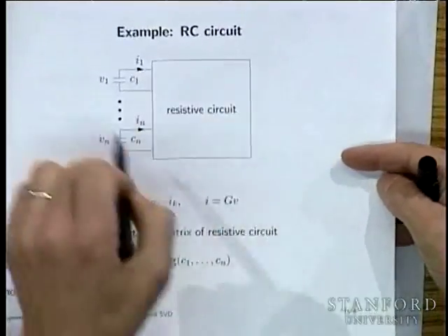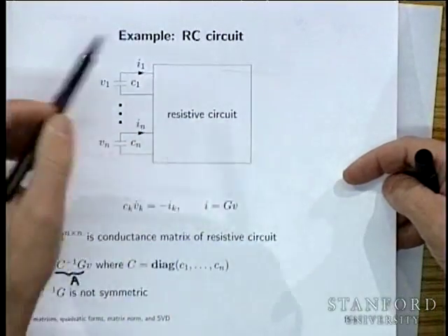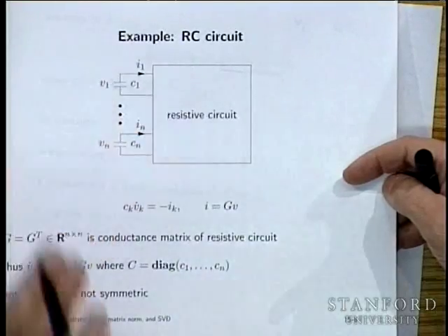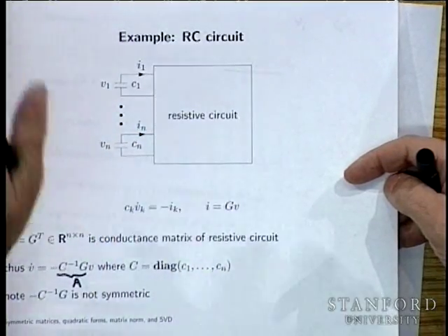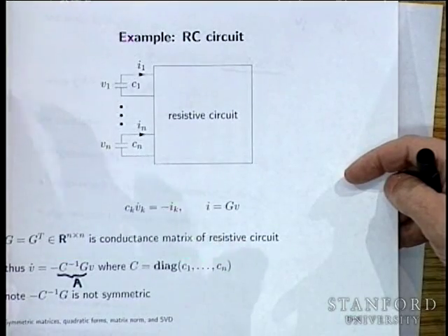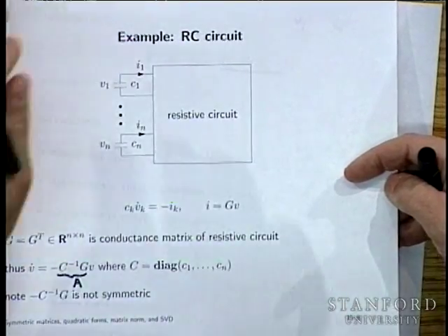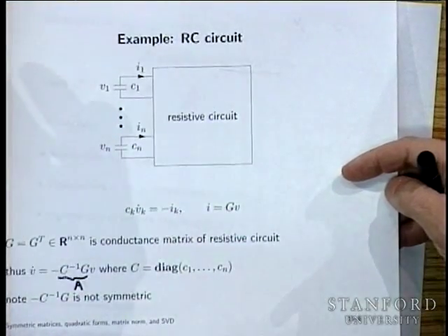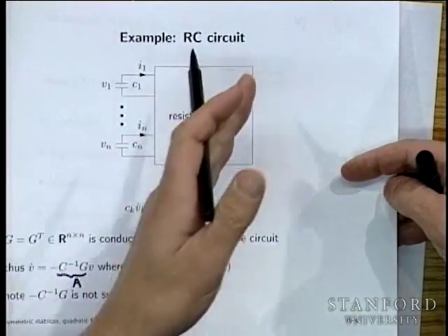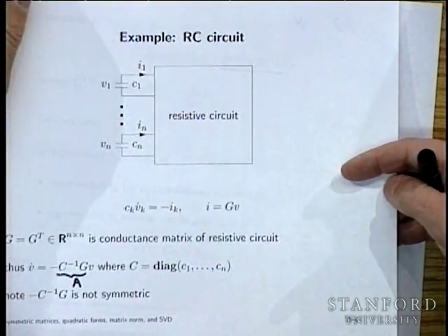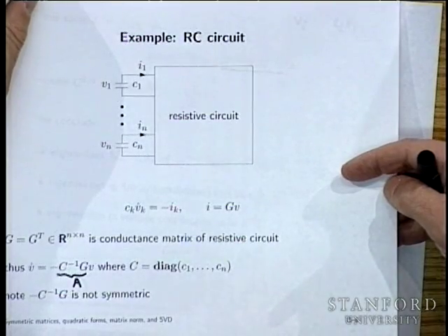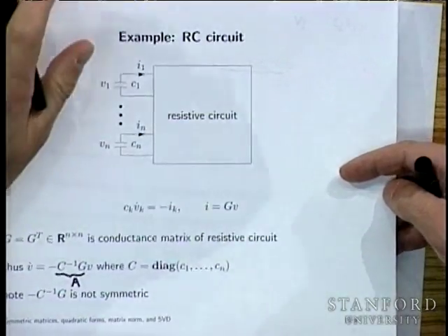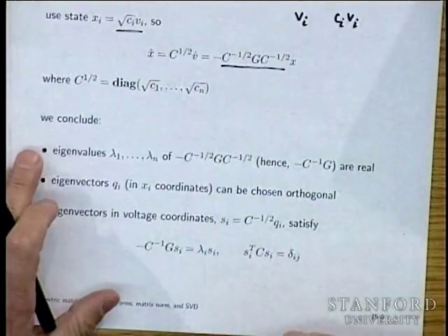So we recover something you probably know from undergraduate days or intuition or something like that. An RC circuit has real eigenvalues, period. So you can't have oscillations. Okay? Cannot. So for example, in an interconnect circuit, if it's well modeled by resistance and capacitance, you cannot have oscillations, period. Okay? You have to have inductance to have oscillations. Okay. That's that.